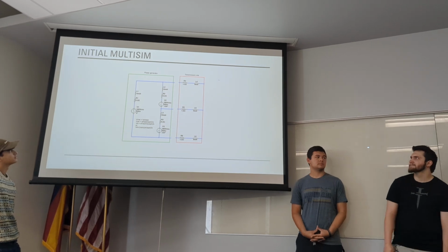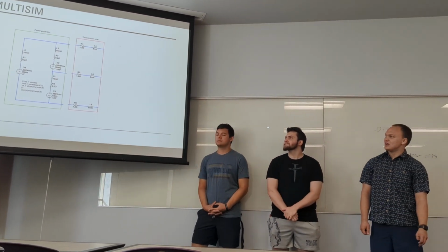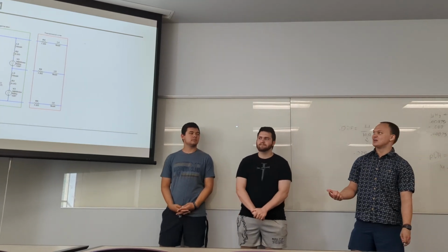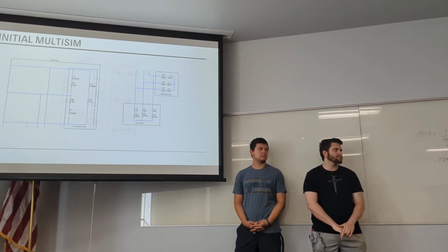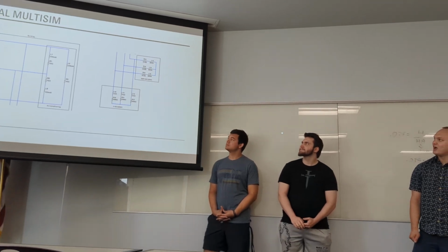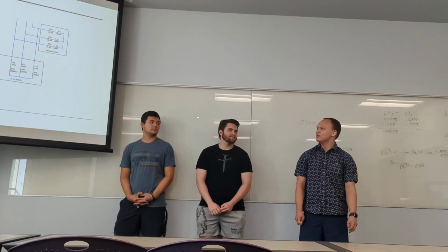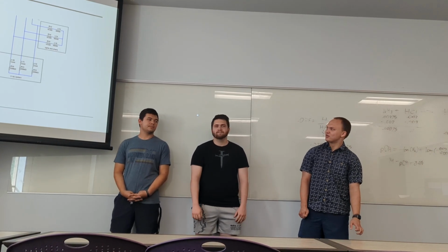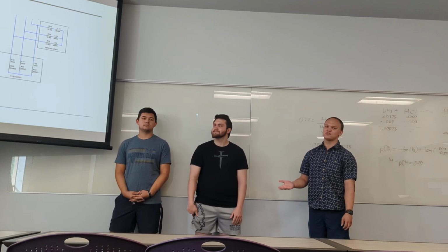So this is our power generator that would be off-site, and this is in delta form, so we had to convert that to star form. Then our transmission line has some resistances to it, and that leads to our loads, which in our case is the air conditioning unit, some lights, the outlets in each room, and our x-ray machine that we're going to change later on to our own medical device. And again here, the air conditioning is in that delta form, so we have to change it for all of our calculations.